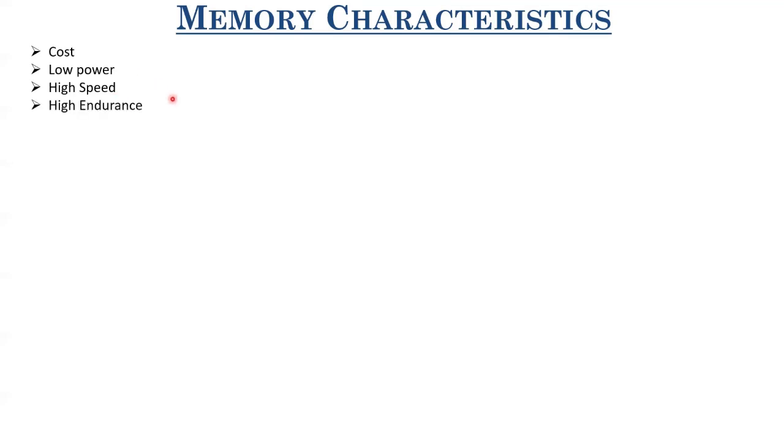It should also have high endurance. Endurance is basically the number of cycles for which the device works perfectly. As I told you, in flash memory you have that tunnel oxide, and you're forcing current through it. So after 10⁵ cycles of operation, that tunnel oxide degrades. Operation of the device is affected. It may even break down.